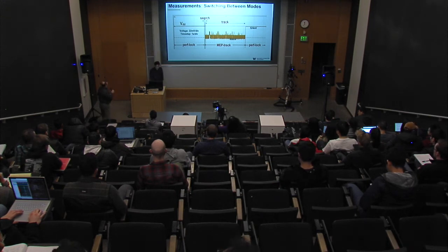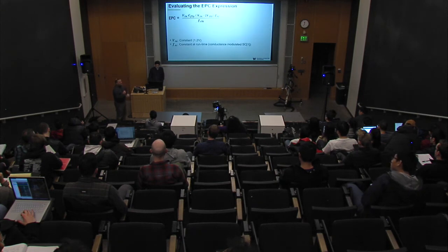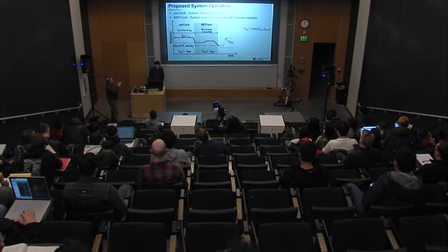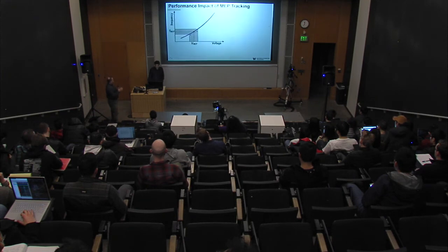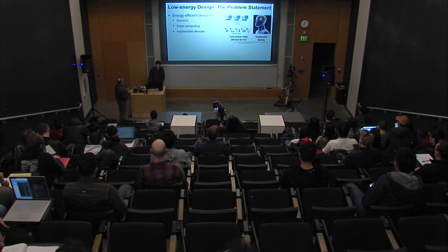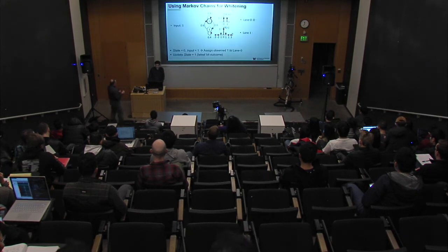I have a question. On the random number generators, what is it called? Von Neumann correction. That helps you with offset, any offset that's in the comparator itself. But how does it help you with the bandwidth question? Because the comparator still has limited bandwidth, and I thought that was leading to it.